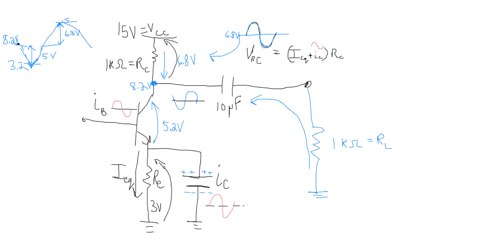Remember, we have to think about what the base current is asking for. We're assuming that it wants only 5 milliamps more. So 2.5 volts is sufficient to get that additional 5 milliamps from both the resistors, collector resistor and load resistor. So remember, we have the picture of the 2 of them in parallel when it comes to the AC model.